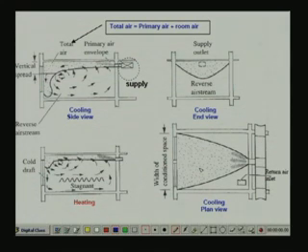Let me show a schematic of airflow patterns using high side outlets. You can see here that this is where you have the supply air duct and supply air is coming like this. So, you have the primary air envelope, this dark area is your primary air envelope. This jet leaves the supply air outlet at high velocity, and as it leaves, it entrains the room air.